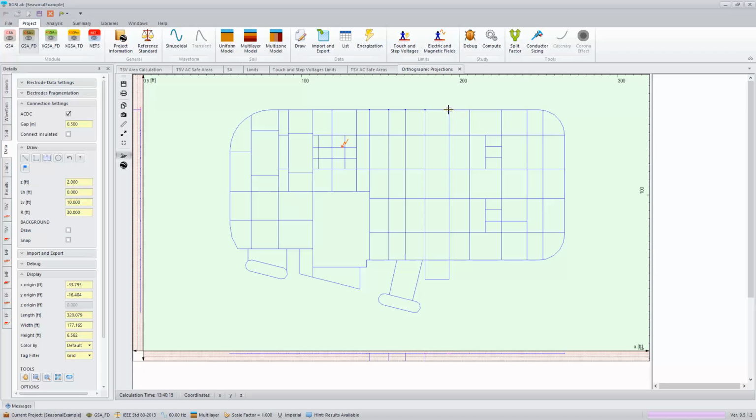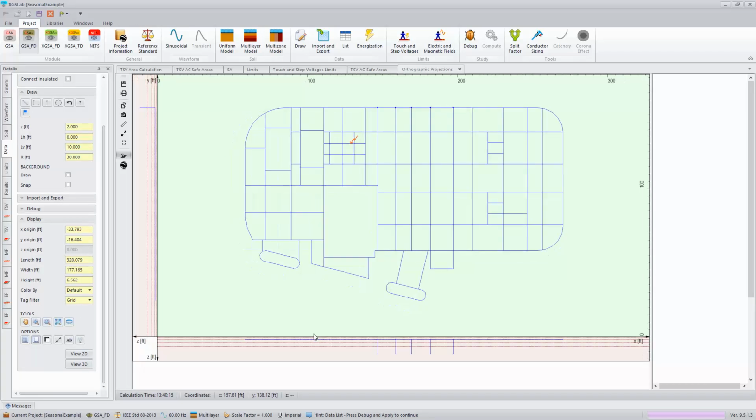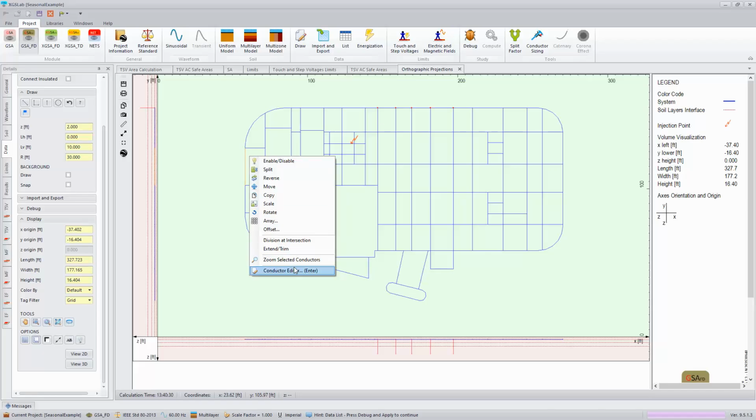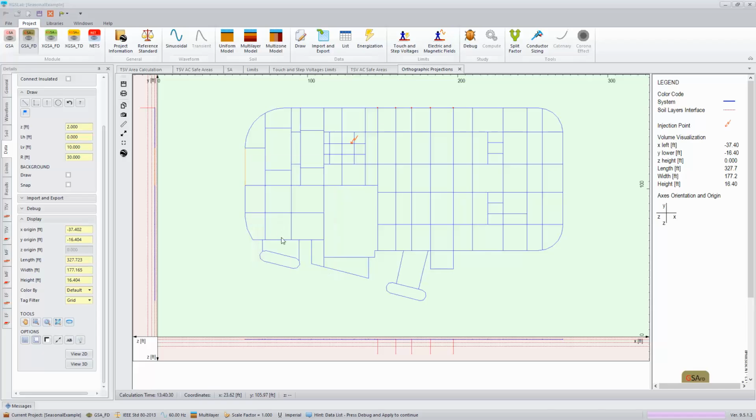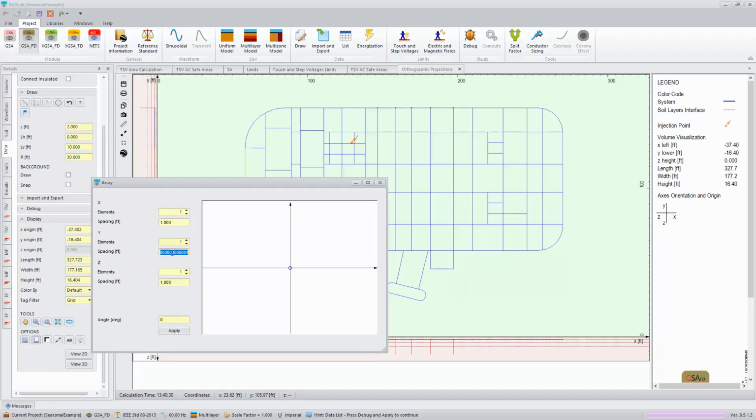And what I'm anticipating is that in the areas where we have these ground rods inserted, we're going to see better results. It's going to help us maintain contact with the soil that's not dramatically affected by the seasonal variation in temperature, and it's going to help us reduce our overall ground potential rise for that system. Just apply this.